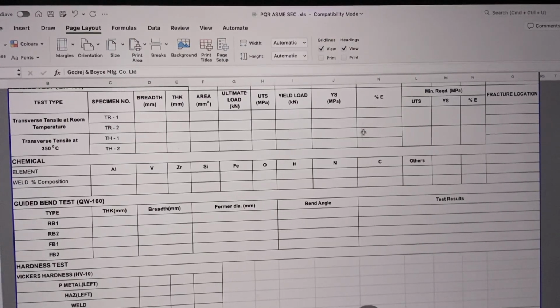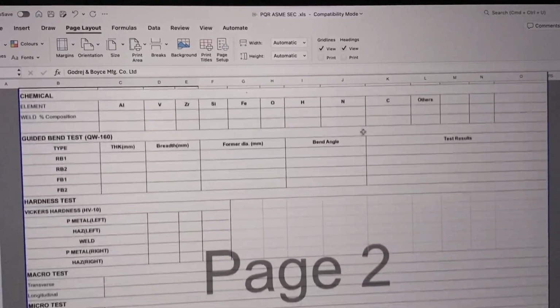You have better machines now where you get stress strain diagrams very nicely done by the machine itself, and a 0.2% offset is also given through the program. However, just because it has been done by an automatic machine or by software, don't assume it. See to it yourself, counter check that everything is okay, and then only sign or certify on those materials.